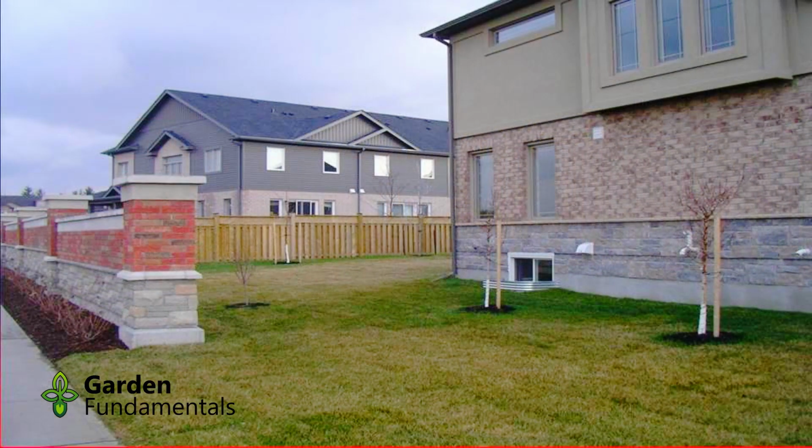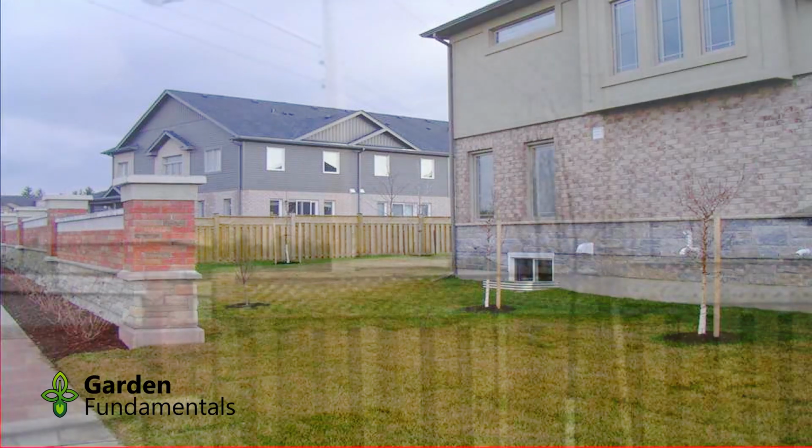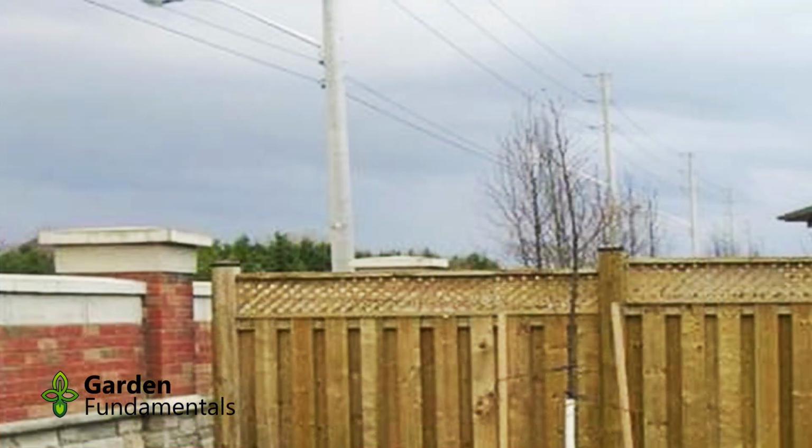And that was put in on purpose. All the water runs down to this spot, and then it runs along the brick wall to the street. And that's how the water leaves the property. So the slope in this area is pretty important. If I want to know what the slope is, I can just measure the drop in the top of the fence posts here. Fence posts are 8 feet apart, and the drop between each one looks like it's 3 inches, 4 inches, something like that.